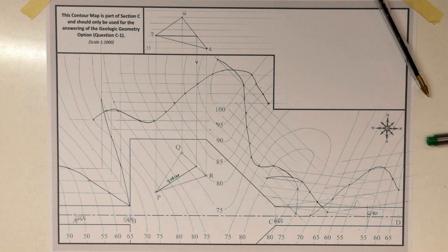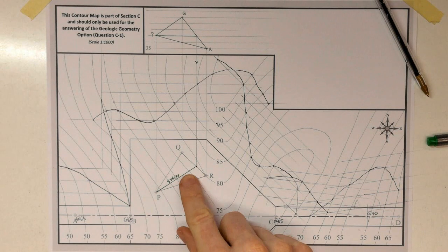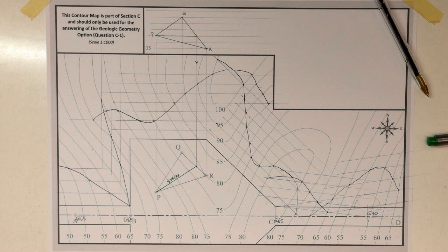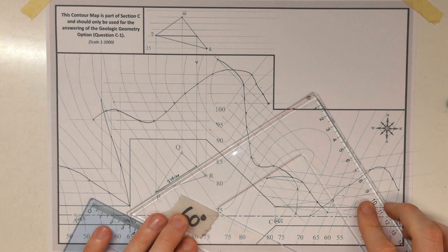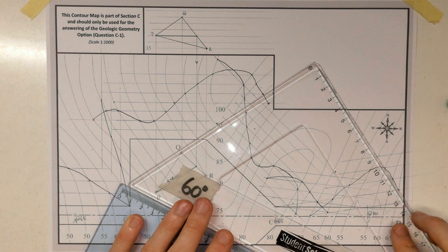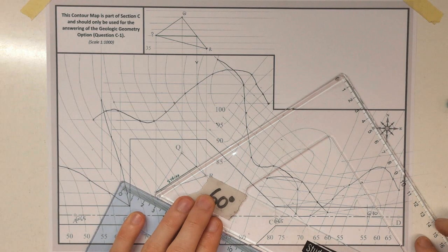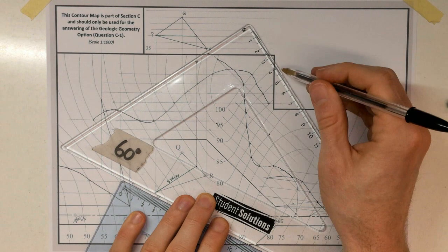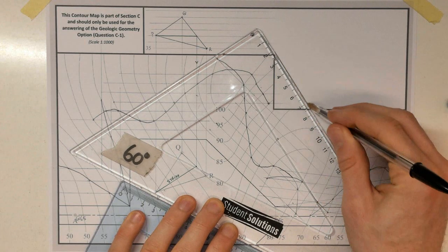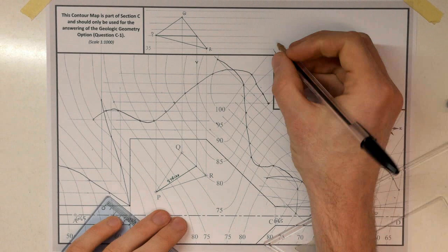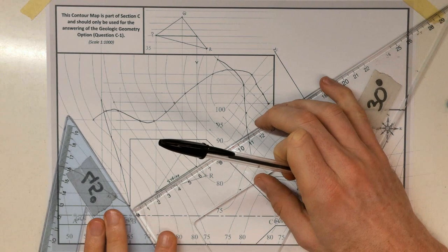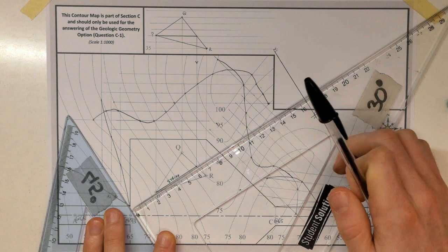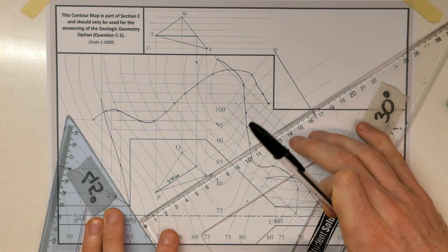Okay. Now they want to find the dip, so I want to see this plane as an edge view, so I need to see the strike as a point view. So anywhere out here, I suppose in the white space they've got provided first there. Go 90 degrees to my strike, a little bit further. That's my X and Y line, and we'll check everything out. P2 and R.